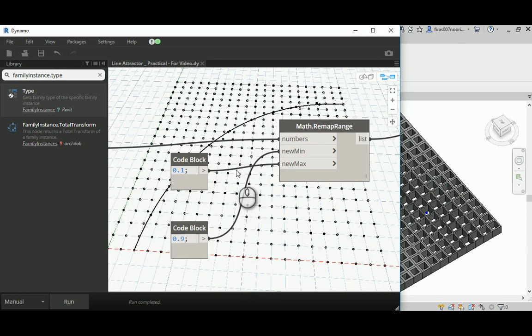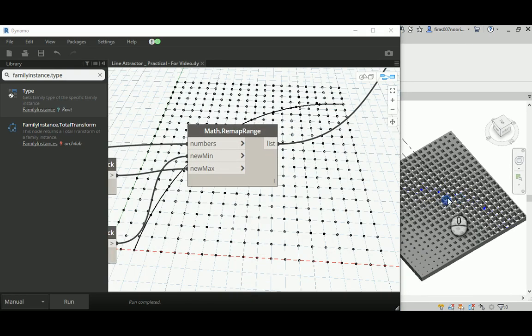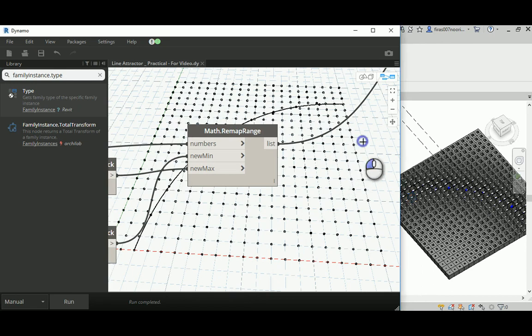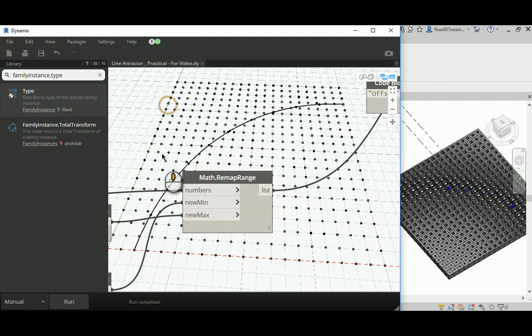As you can see, I'm not really happy with the grid because it's less useful for architects to work with. We prefer to have a wall, for example, and then let Dynamo divide it for us, and then clad it with these patterns. That means we need to get Dynamo to select elements from Revit, and then maybe select the line drawn in Revit instead of having these ugly 3 points. Very basic, to be honest. Maybe we select more complicated lines and then let Dynamo do the attractor thing for us.